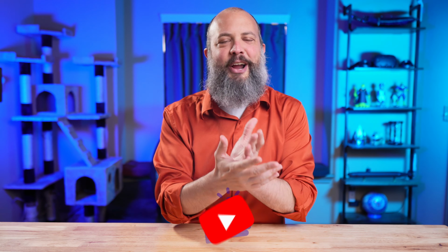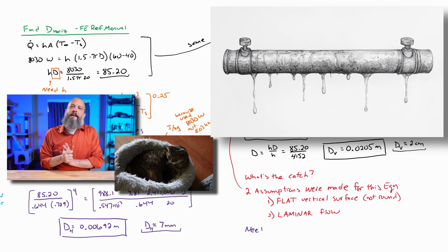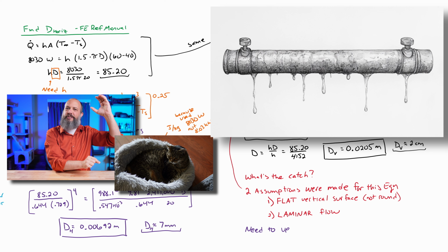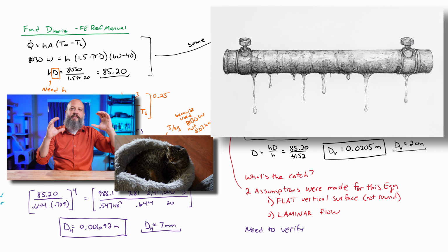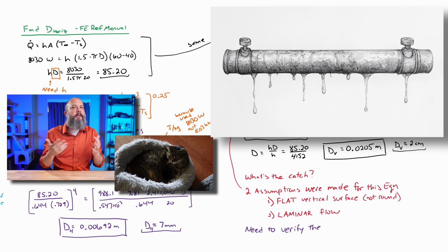At first that's almost sort of weird, like what flow? This is just condensation. We're not talking about the liquid traveling. And that makes sense for a horizontal pipe. With a horizontal pipe, when you have condensation, it just falls off the pipe after it's a liquid. Even if it condenses on the top of the pipe, it rolls off the side and then falls off. That is what's nice about a horizontal pipe: the liquid just falls off. It doesn't flow along the pipe.